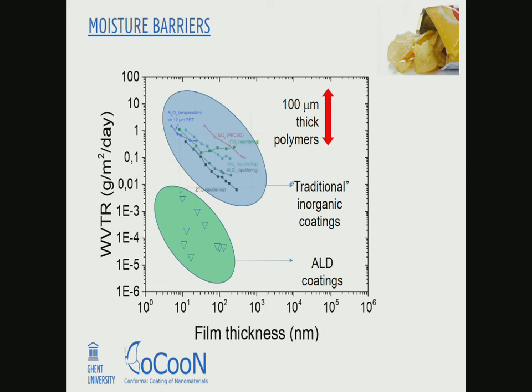Of course, these are very difficult things to characterize and to test, and very long measurements. But anyway, these are the numbers that you can find in some papers that have been reported for ALD coatings, and you can see that the very nice conformal nature and the pinhole-free nature of ALD enables much better inorganic barrier coatings. So for much thinner films, you already have a much better barrier than for many other techniques for depositing inorganic coatings.